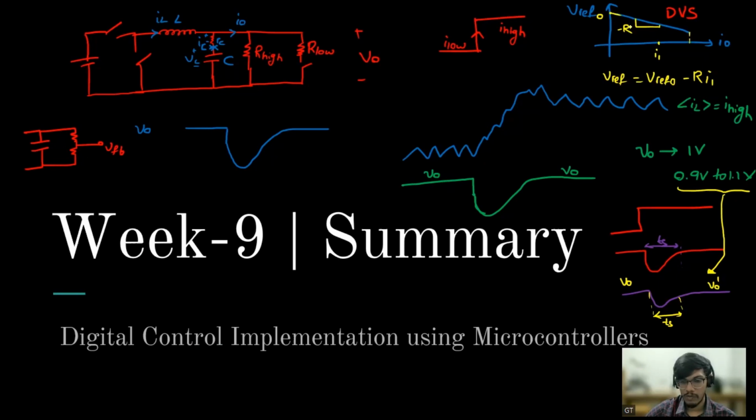So the main intention of this is to make sure that our output voltage requirements are met, so that it will lie within the range that it is supposed to be in. Also, I am dynamically changing my V0 so that, say at this current, if I reduce the V reference, it will not take much time to come back to this voltage. It will be quickly coming back to this voltage. So it is to reduce the settling time and also to make sure that V0 is lying within this range.